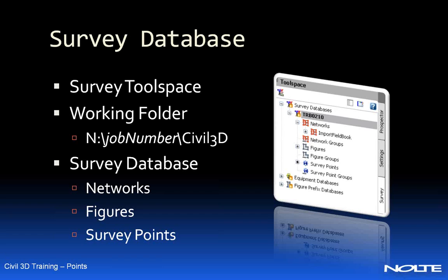So this becomes the tool by which we can manage our point data and get it into multiple drawings. And if you attended the session a couple of weeks ago on points, we saw that all the point data was created in the drawing file we were working in, and there was no way to share those points with any other drawing files. Well, the survey database becomes a way that we could possibly do that.